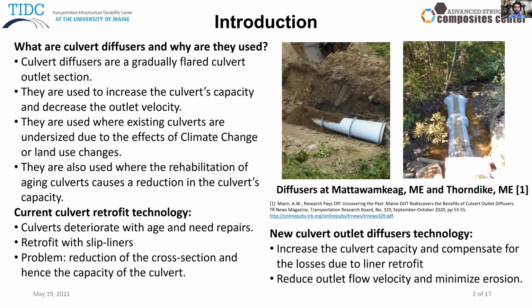Hence, the cost associated with manufacturing the new culvert, digging up the highway, removing the existing culvert, installing the new culvert, backfilling and resurfacing can be avoided by culvert rehabilitation technology. Furthermore, the highway traffic disruptions that are caused by culvert replacement can also be avoided. The diffusers improve the culvert flow, which would enable effective rehabilitation, preventing long-term highway closures to replace these 50, 60 years old culverts at tremendous costs to the traveling public.